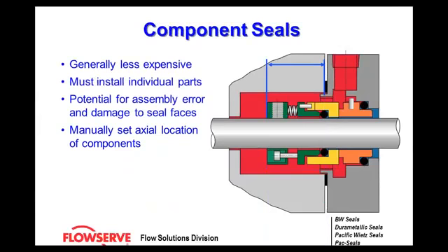Okay, right there, from the stuffing box face or the case of the pump to somewhere along the shaft. That distance is your setting distance, also known as, some people refer to it as, seal crush. That setting distance has to be manually scribed on the shaft, manually set.